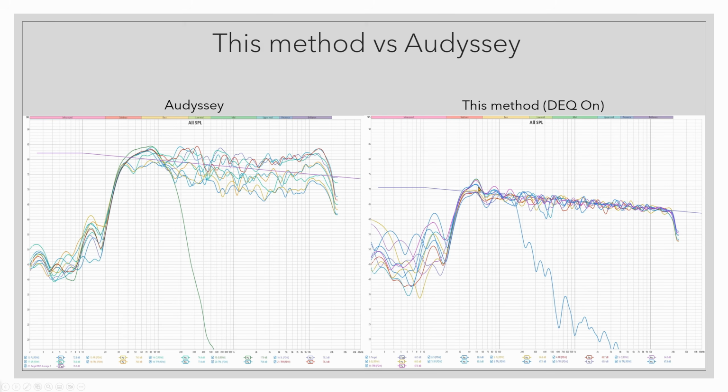The tiny peaks here in fact are not even present. They're caused by the dirty electricity 50 Hz hum in this apartment. The speakers are all crossed over above 50 Hz, so the response here should only be the subwoofer response, but every measurement, depending on the phase at 50 Hz, gets different responses, so there is no peak here. You can be certain of that. This is not a calibration error. But look at the difference.